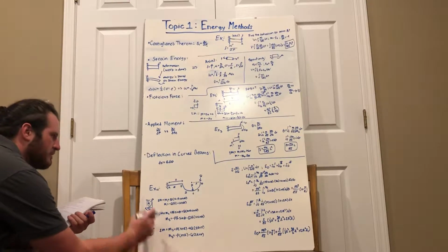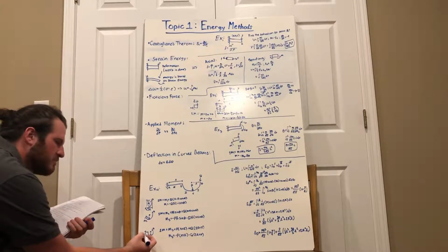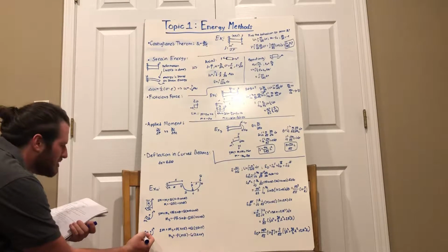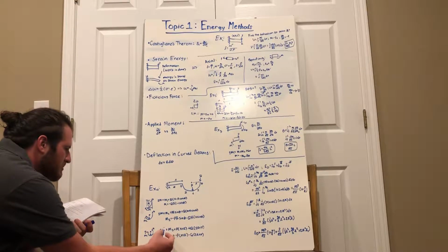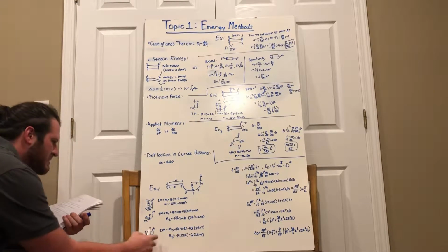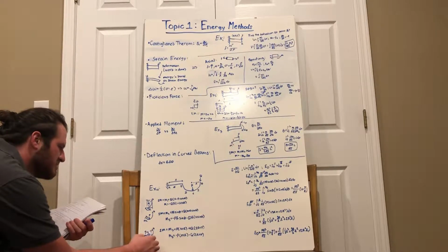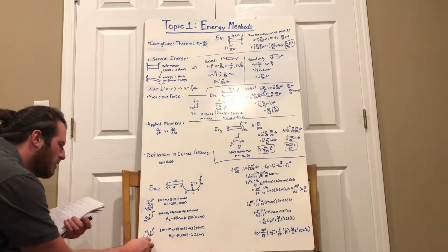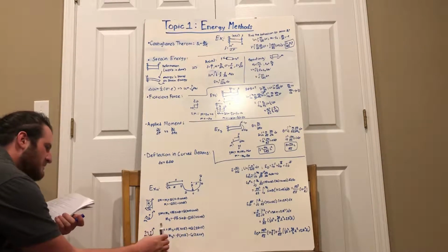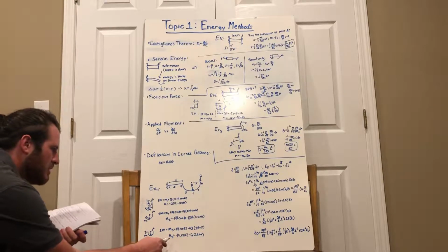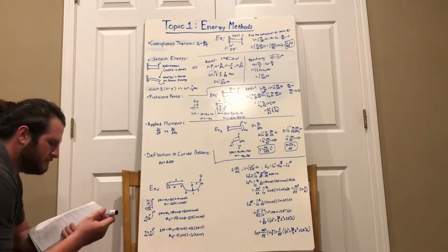Let's do it for the third part. This time we're on the straight path, so we can think about using something linear. Let's cut it again and do our moment. Our sum of moments is going to be M3 plus P times x plus r, x plus this radius to get to this P, plus Q times 2r, so twice this radius, plus x, the distance of the cut. Rearranging, we'll get M3 equals negative P times x plus r minus Q times 2r plus x.